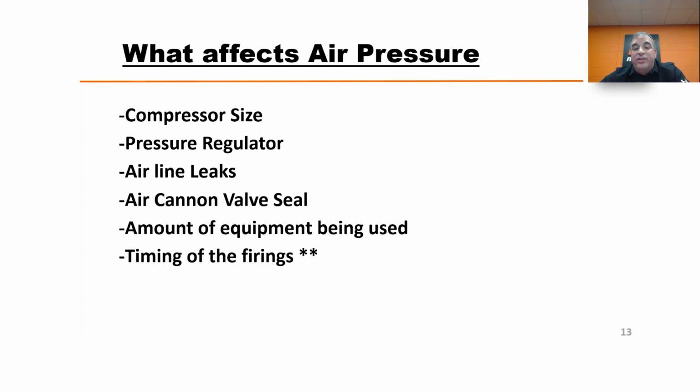The valve seal itself, there's some sort of piston or sealing system inside that valve that will block off the discharge and allow the tank to be filled. If that seal isn't made, then it's just like a large air leak.